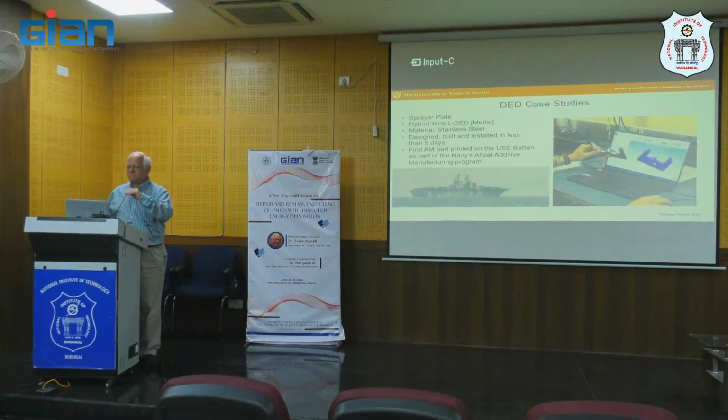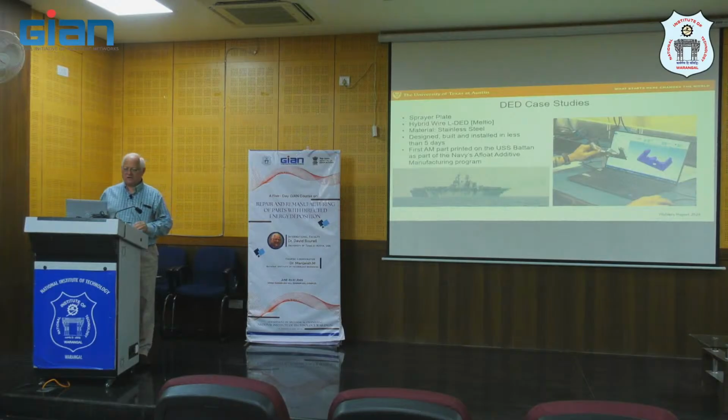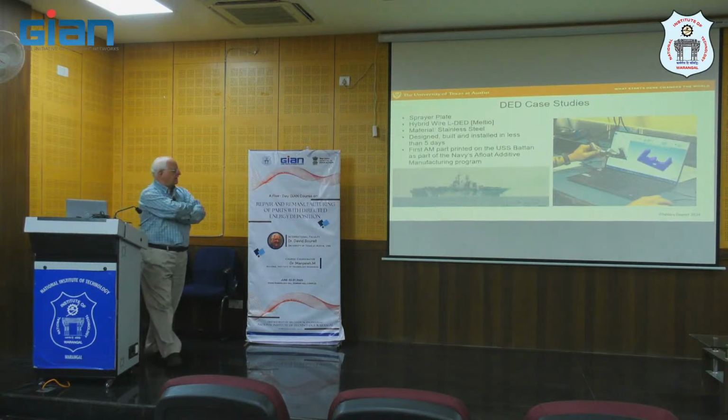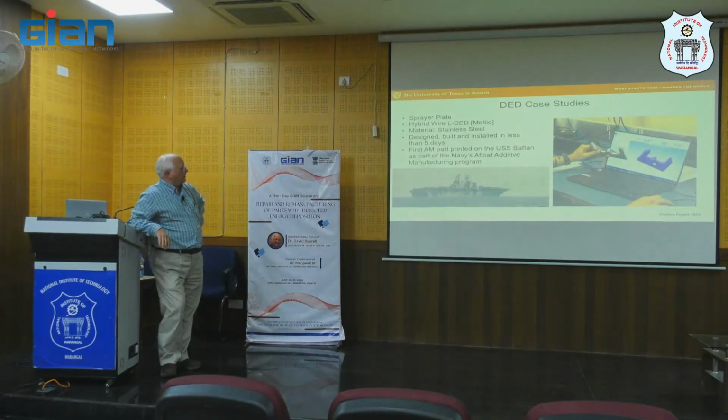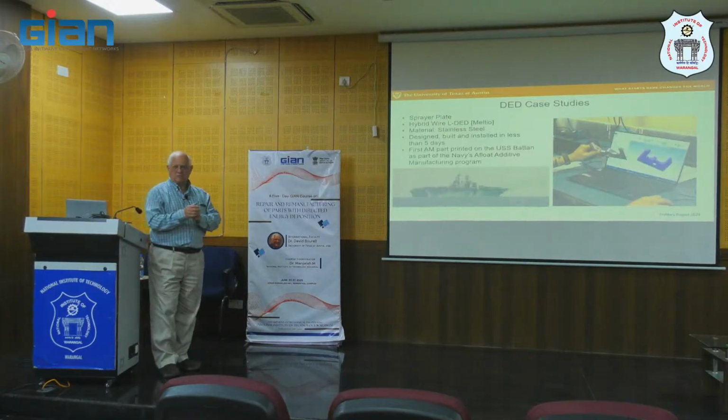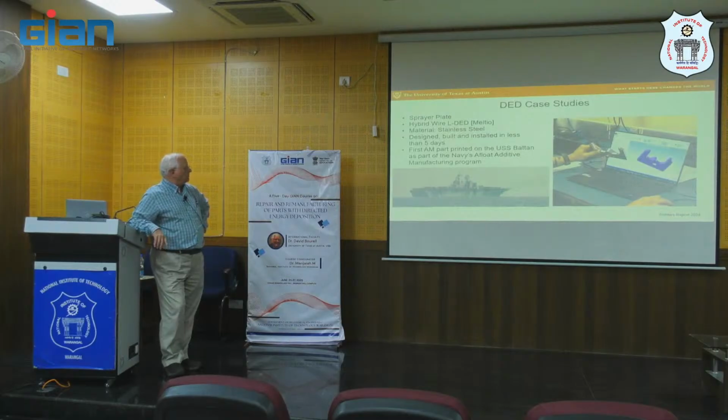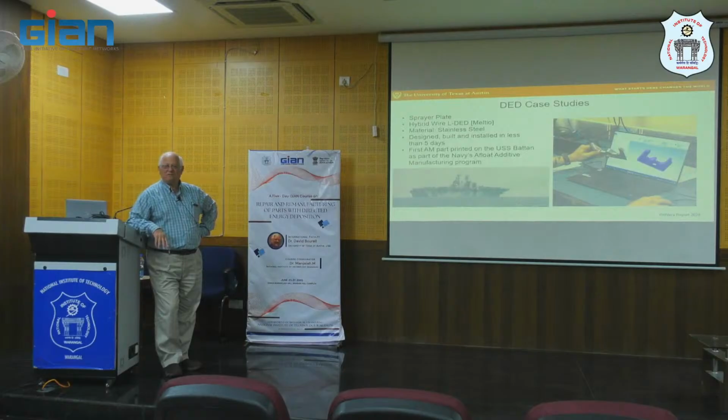I wanted to look at some case studies for additive manufacturing now. So we're moving away from hybrid and repair into some case studies. This is an example of directed energy deposition. The plate you see on the far right is what this case study is about. It's a sprayer plate made by laser-based DED stainless steel, and they designed, built and installed the plate in less than 5 days.